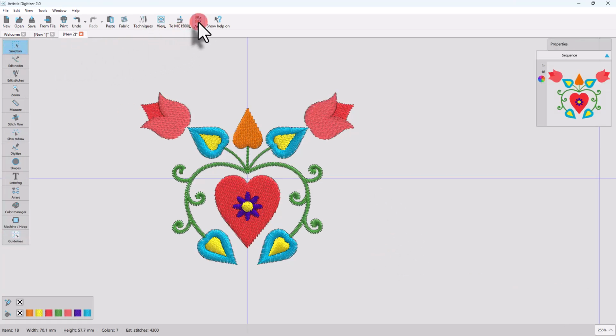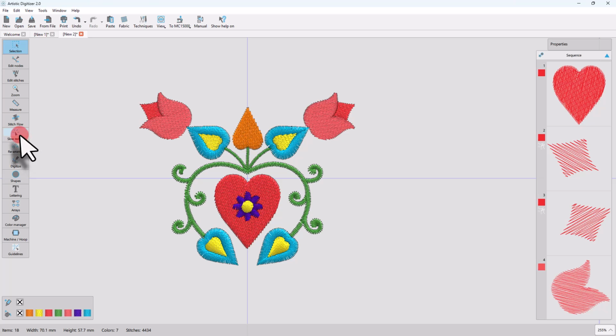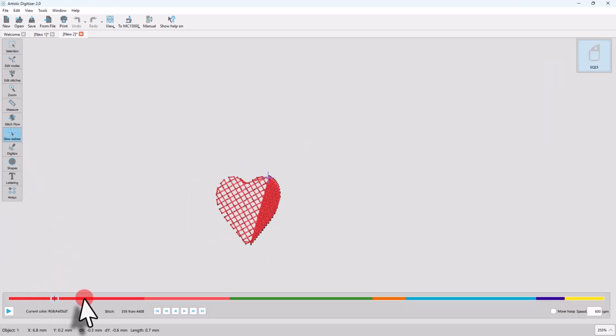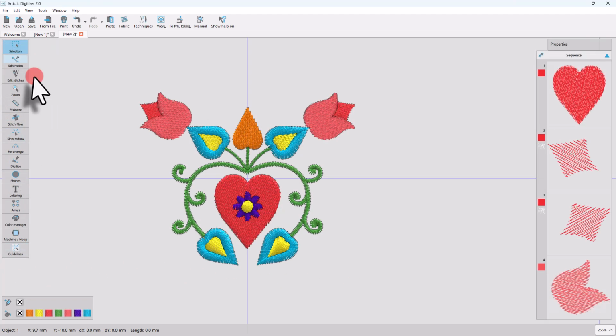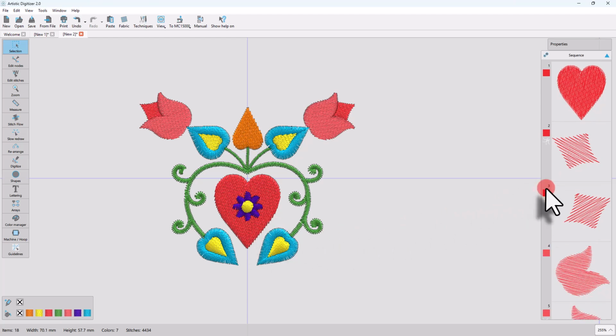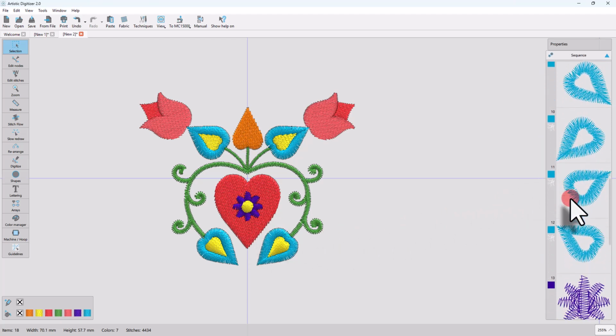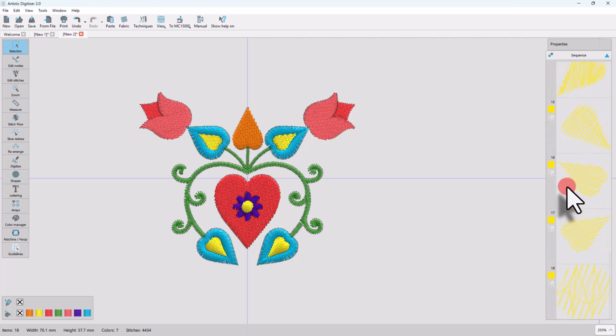If you switch to manual mode and go to slow redraw, you will see the same sequence as before. This happens because when switching to manual mode, the optimizer rearranges the objects according to the optimization strategy that is already set. But now you get a separate icon for each design part, and you can drag any of them to create the sequence you like.